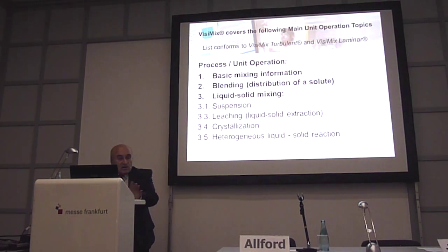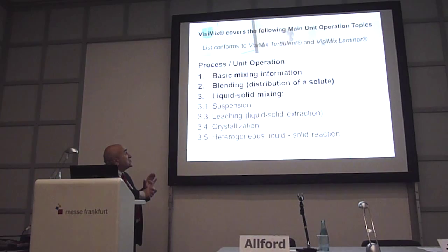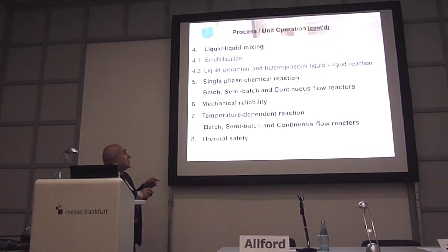This whole VisiMix set covers the following main unit operations. As one can see, it includes single-phase mixing, two-phase mixing, including liquid-solid mixing, liquid-liquid mixing, liquid-gas mixing, I forgot to include it, single-phase chemical reactions, mechanical calculations of the shaft, and temperature-dependent reactions, including thermal safety.